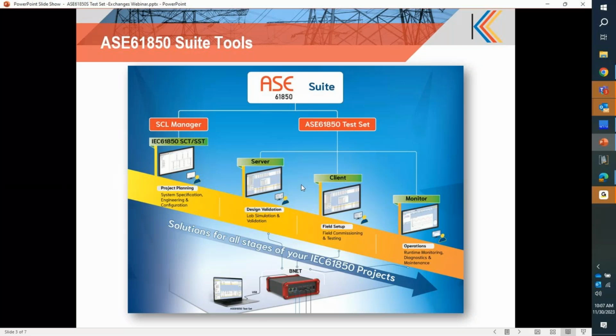And the server and client are part of the ASE61850 test set. The client gives you MMS capability to communicate with server instances and actual IEDs. And the IED Smart that I mentioned is the advanced IED simulator. And we have monitoring capability with our tools. So after commissioning, when you're performance monitoring or debugging, you could passively monitor communications between devices, and retrieve GOOSE information or GOOSE report messages and reports.